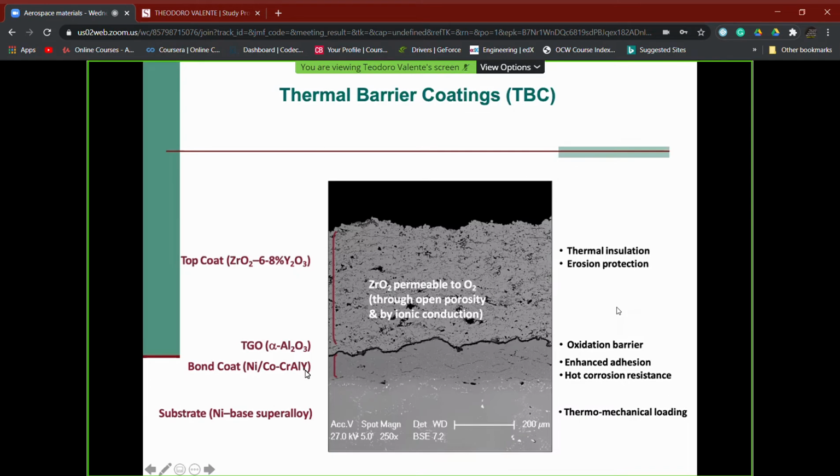it's true that the most reactive species is aluminum, forming aluminum oxide during service. But it is also true that we have met chromium, for example, in high temperature steels, and we remember that chromium is able to react with oxygen to form chromium oxide. Remember, for example, the passivation state in stainless steel.